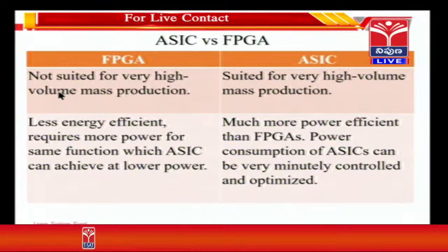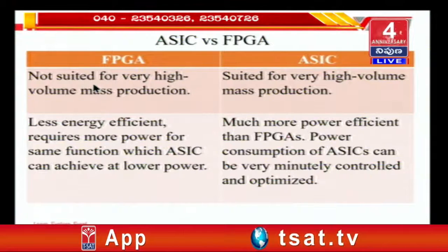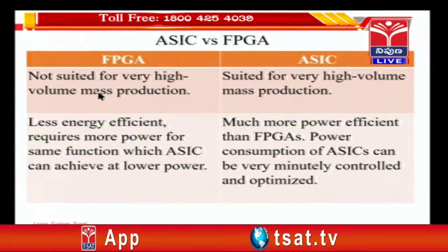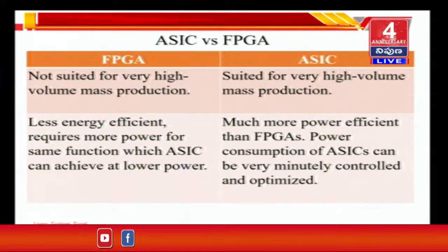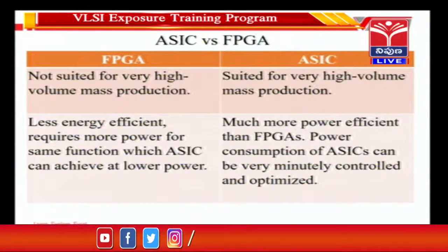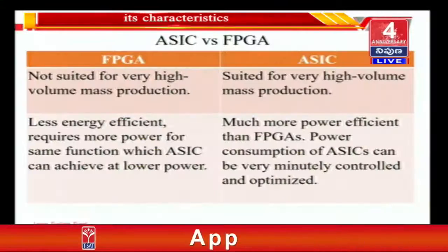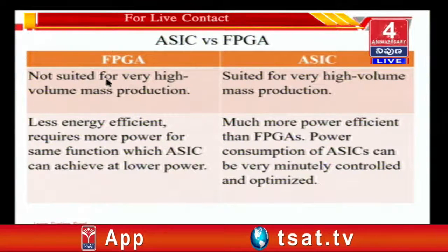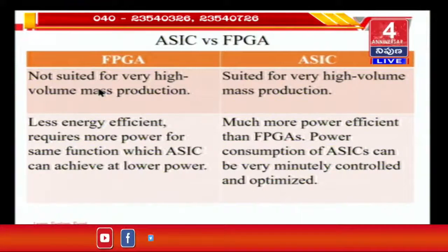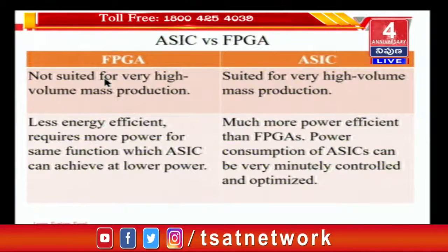FPGAs are not really suited for use in high volume mass production, in the sense that if you want to sell a product in which a large functionality is to be embedded, then that FPGA is not a suitable part for use in that particular product, because FPGAs have a lot more logic, a lot more circuitry, a lot more interconnect resources than are actually required by the function.